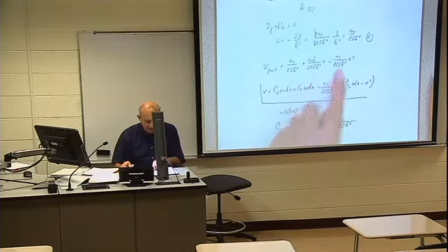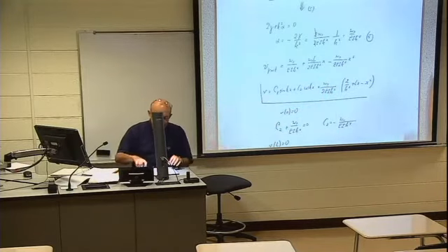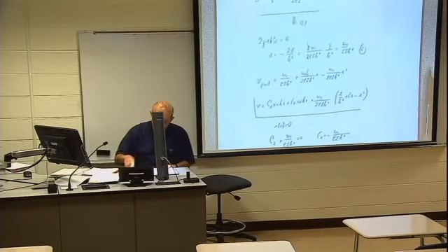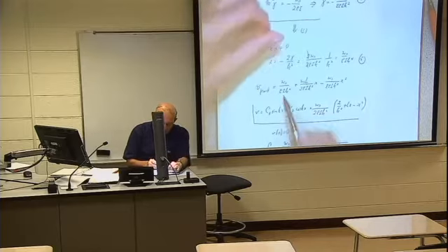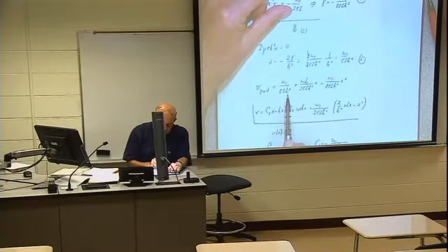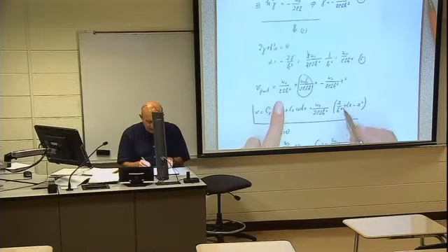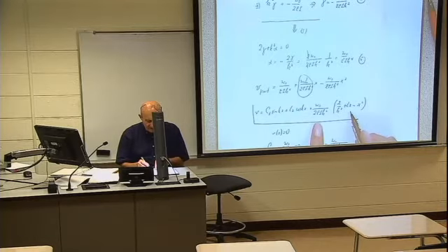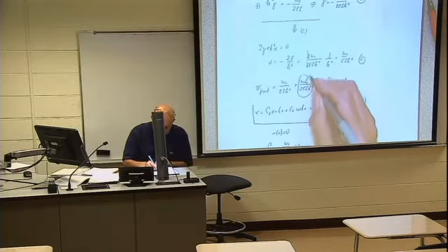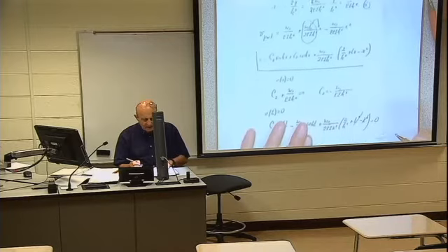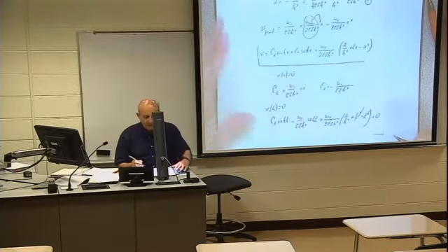So that is this V particular. Now V, that is complementary solution plus particular solution. I just took out from here W0 over EI k squared, which appears everywhere. So I took this coefficient everywhere. Then here will be 2 over k squared, then plus Lx, that is this here, and minus x squared. Once I have this, I have to satisfy now the boundary conditions.